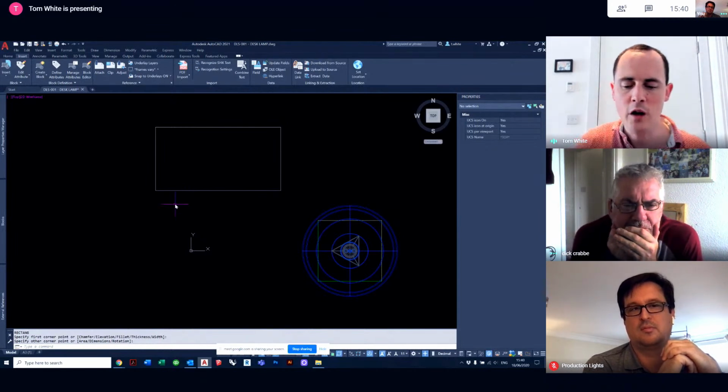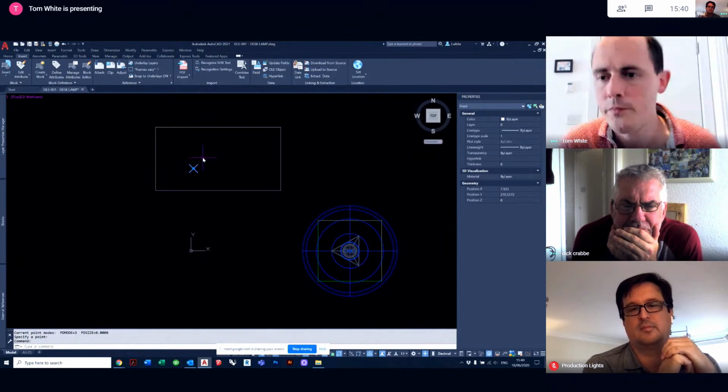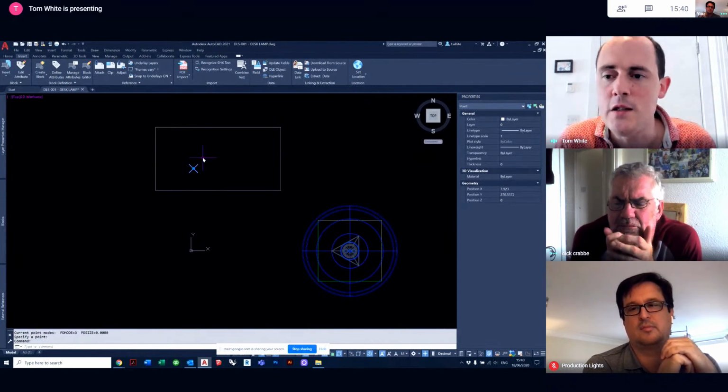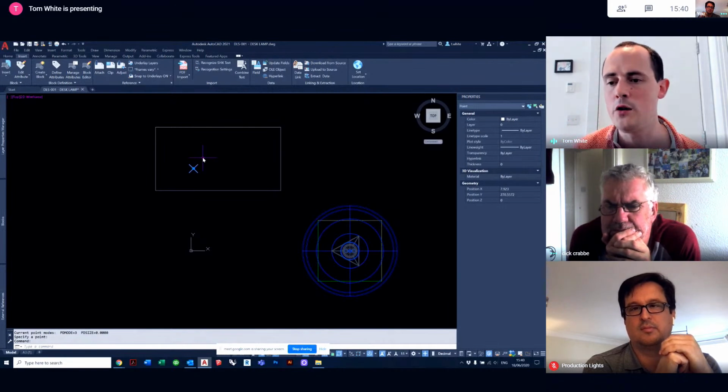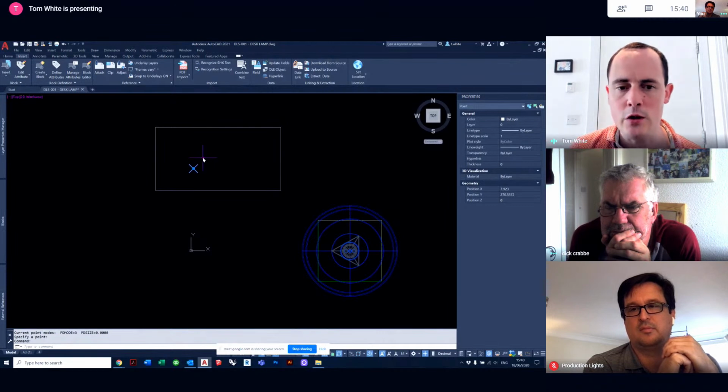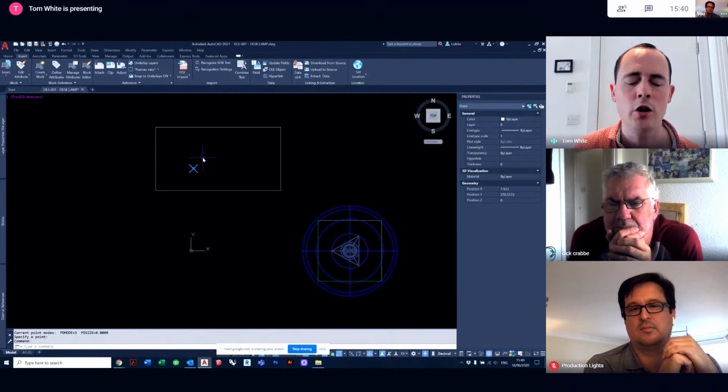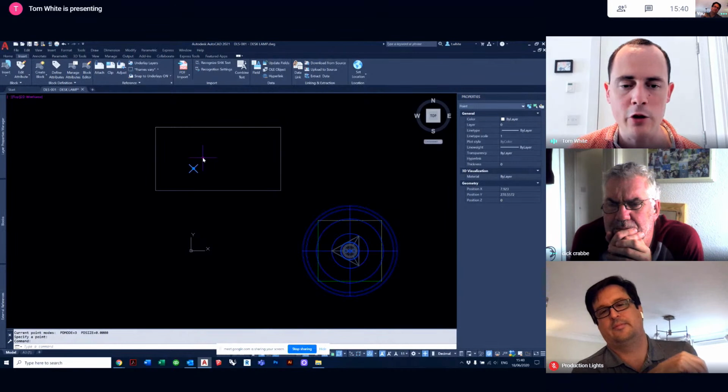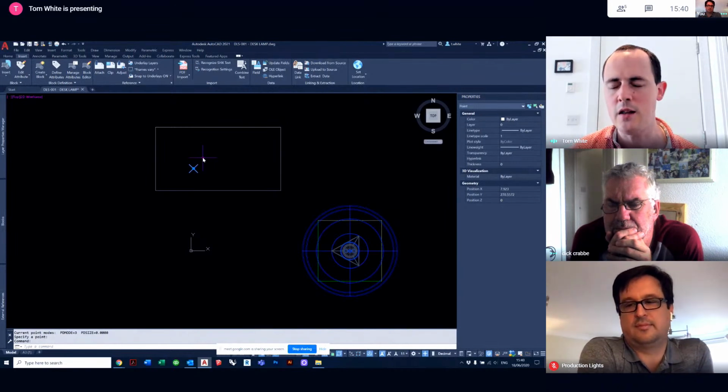So, for example, if I put a point, by clicking point, I'm going to put a point here. I'm going to click on it once. On the right-hand side in my properties window, at the bottom, there's a geometry section, and we have the geometry position of X, Y, and Z. Z is an easy one to talk about. Z is towards me or away from me. In this circumstance, because I'm looking in 2D, it doesn't actually matter, but it could be the height of a chair, or the height of a steel deck, as we discussed the other day.